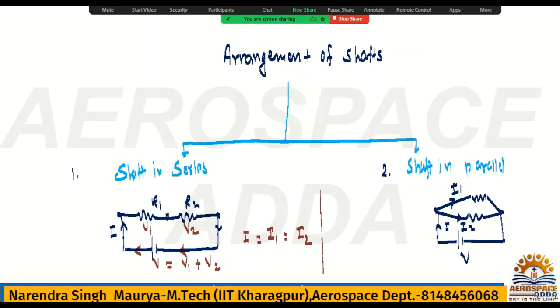But if you talk about this parallel, here for the current you have two closed paths. Suppose this is A and this is B. To reach from A to B in the series, we have only one path, so current will follow only one path. But here to reach from A to B, we have two different paths. This is R1, this is R2. One path is through R1, another path from A to B is through R2. So definitely current through R1 is I1 and current through R2 is I2. So whatever the total current I, this will be the sum of I1 plus I2.